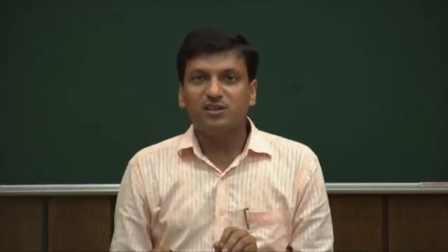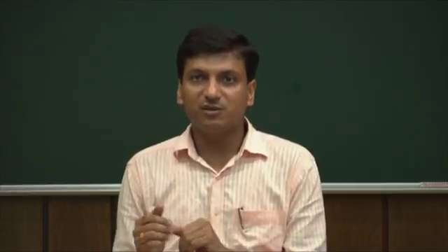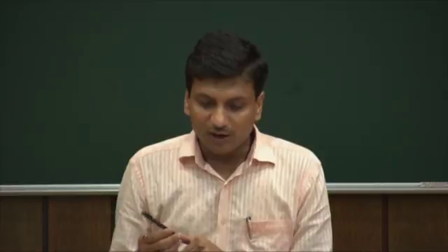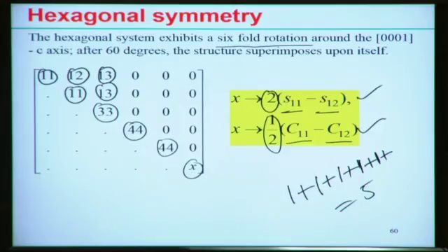That means it depends on the relationship, either strain in terms of stress or the reverse, stress in terms of strain. So accordingly this constant term varies. This is to be noticed here. Be very careful when using this, whether we are representing the equations in terms of compliances or in terms of the stiffness matrix.